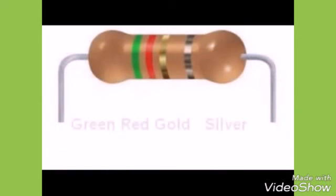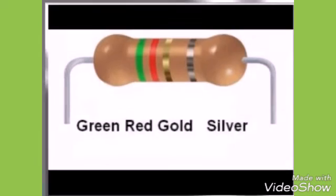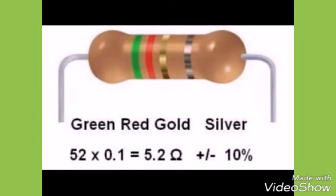Here is another 4-band resistor with low-valued resistance. Its colors are green, red, gold, silver. Green is 5, red is 2, gold in the third band is a multiplier of 0.1. So the code reads 520.1. And so we multiply 52 by 0.1, giving a nominal value of 5.2 ohms.